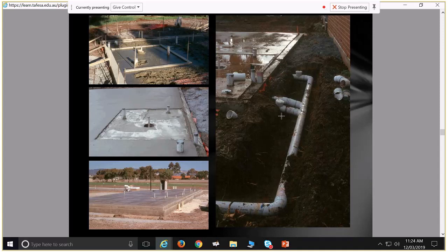Let's say we've got 6 millimetre tiles. On top of that, we're at 76 plus a little bit of tile adhesive underneath. We're probably going to have an 80 millimetre set down. We probably don't want to do an 80mm set down. The reason we wouldn't want to do that is I spoke earlier about concrete coverage, about your mesh and everything. If we're doing an 80mm set down in our bathroom, then all of our mesh in that section has to be down even further, and that requires a lot of detail with that slab.